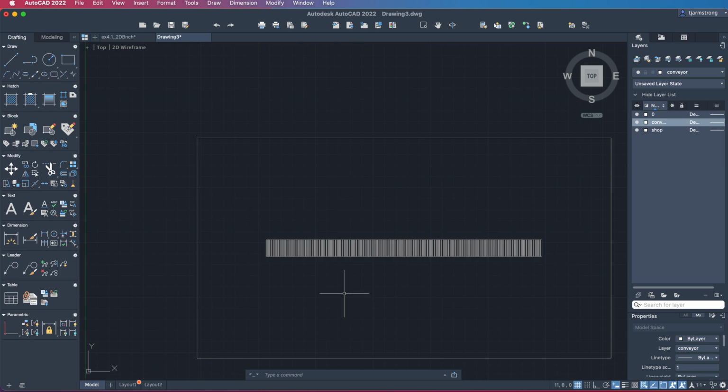We can draw our workbenches the same way we did in exercise 4.1, but one of the powerful aspects of using a CAD tool like this is that once we've created something, we don't have to redo it. We can actually export it, store it in a separate file, and bring it back in, and that's exactly what we did when we created the wblock command earlier on.